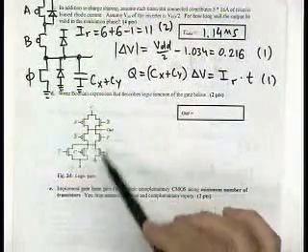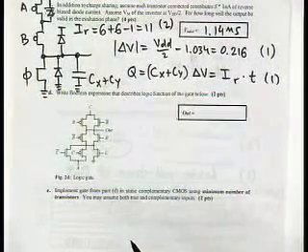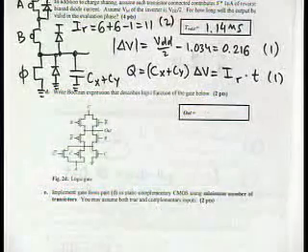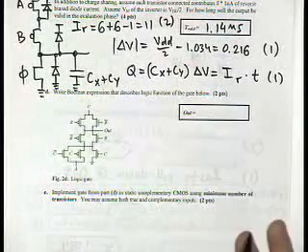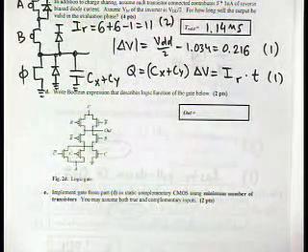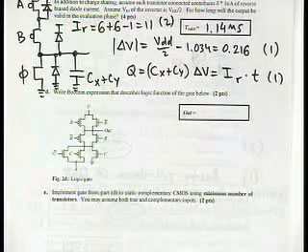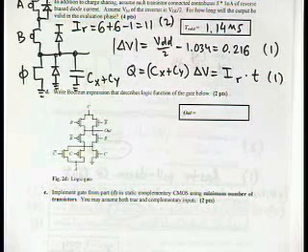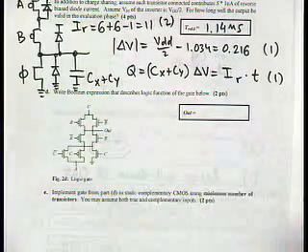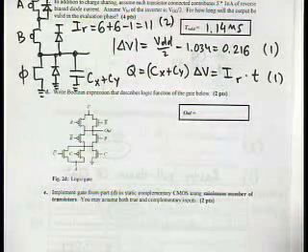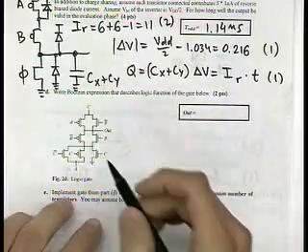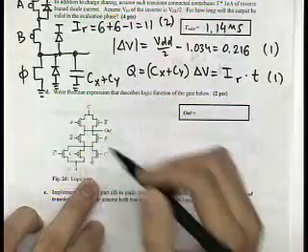So now the strategy to develop is basically you either decide if you want to go with the pull-up network or the pull-down network. If you start mixing pull-up and pull-down, you will likely end up with redundant terms if you don't do any Boolean algebra on top of that. So now let's start with the pull-up. Let's look at the combinations of input signals that we can pull this node up for.